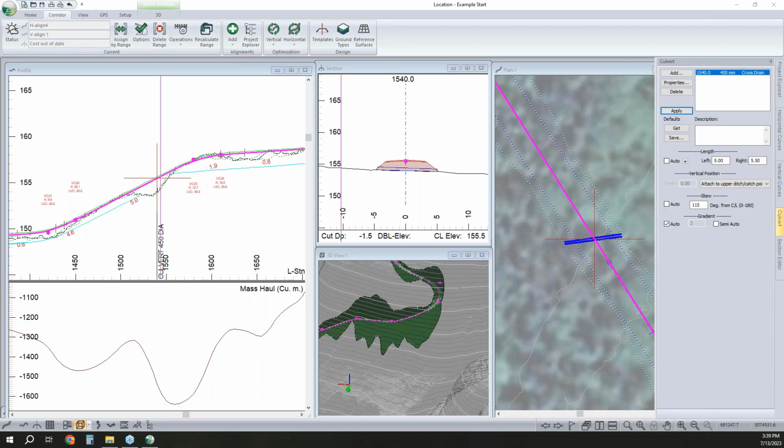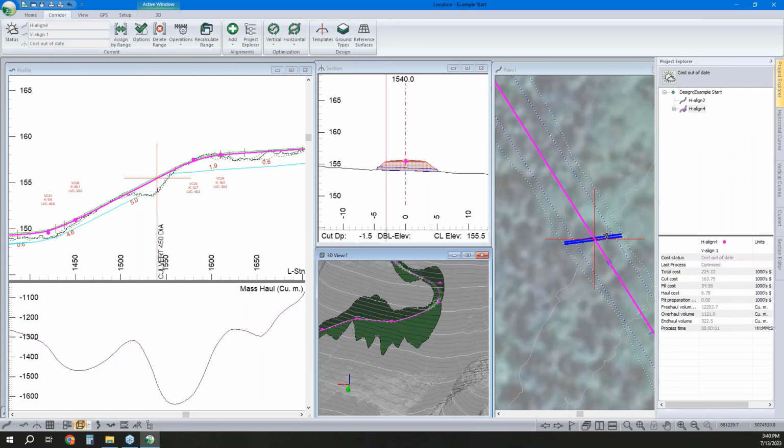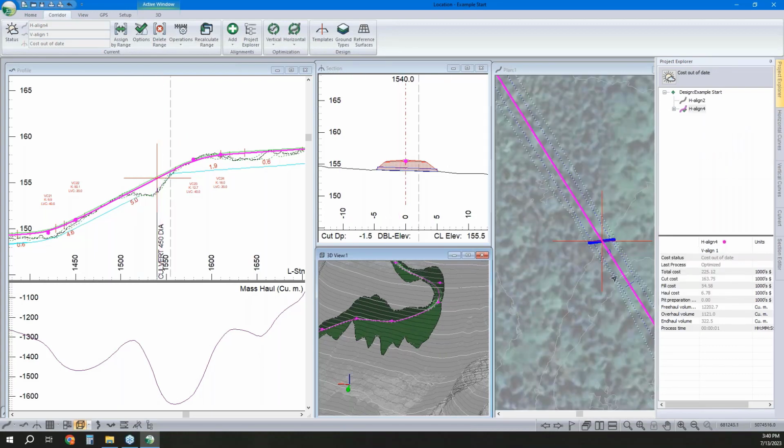And if we wanted to include it in the multiplot, we could show it in the plan view just by displaying it. And of course, I've deleted it, so sorry about that. But then the other thing to do, if we actually wanted things like our cross-section geometry to show up, we could just do it as its own separate alignment with its separate multiplot, and then connect the two multiplots outside afterwards. Yeah, so hopefully that answers the question.